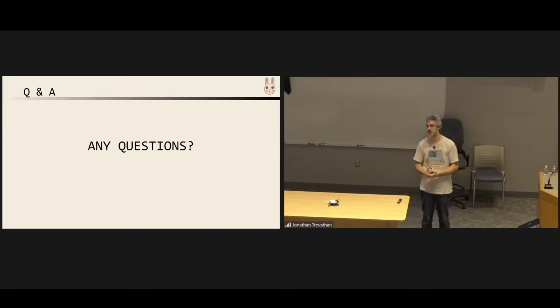And it turns out that the 6AU6 was a really popular tube in TVs. And so I have 2,000 of them at home now. I tend to avoid double triodes. A double triode is just 2 triodes in a single glass envelope, and you have 9 pins that allow you to control those 2 triodes separately. The sharp cutoff 6AU6s that I'm using are just 1 pentode in a smaller 7-pin envelope, so it's a smaller vacuum tube.